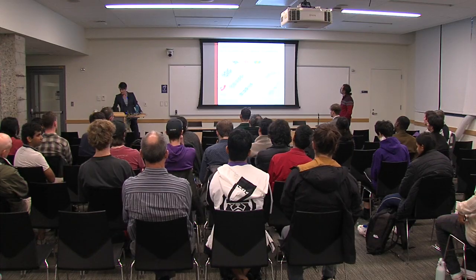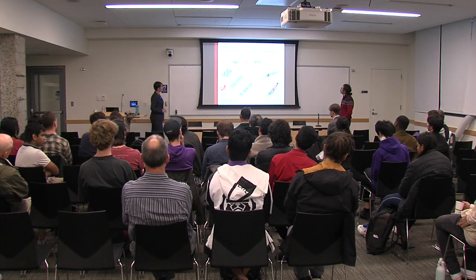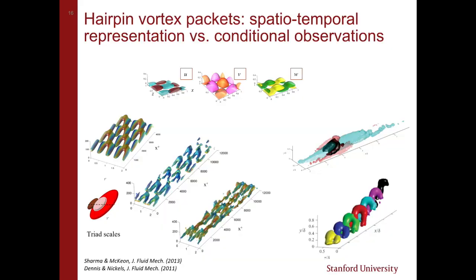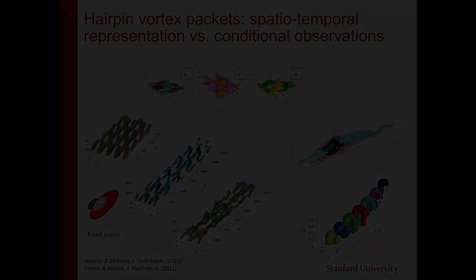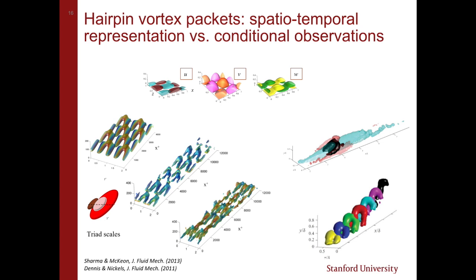Yeah, so, I think if we go back to the place that I showed you, the hairpin vortices, it becomes kind of obvious, right? So there's been a big debate in the literature about this. If I look at a transitional flow, a transitional boundary layer, I will see something as clean as this, right? I'll see these hairpins.